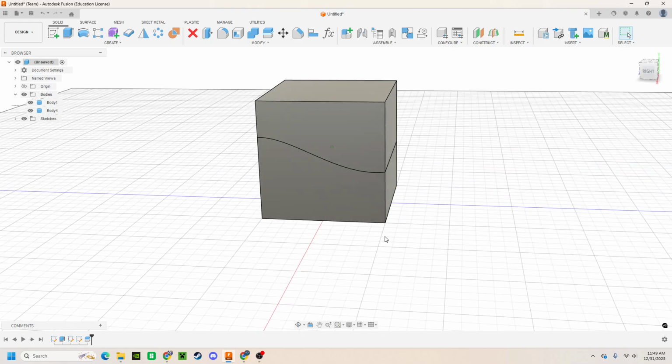Now we're going to be using a new tool called Remove. Within Fusion, there's a very major point of clarification that needs to be made between the Delete tool and the Remove tool. Delete will delete everything that object has to do with your timeline.